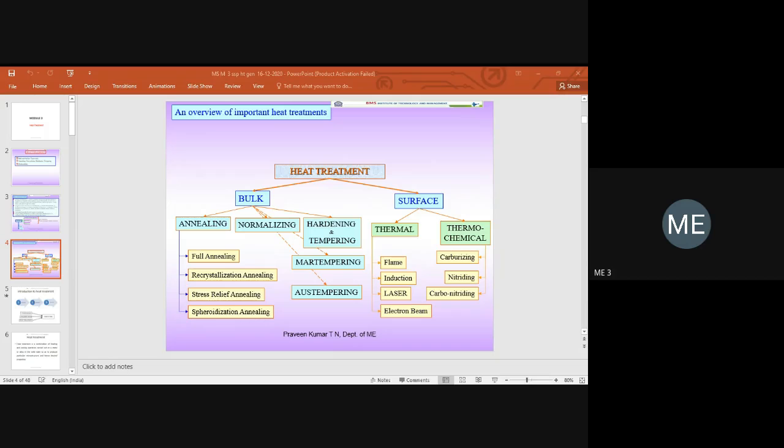As per mechanics of materials formulas, if there is no load, the stress is zero, since stress is force divided by area. But still, some residual stress will be there. That may be produced during your metal forming process, forging process, drawing process or any other manufacturing process. Even during machining, some stresses may be developed in the material. That is about residual stresses.